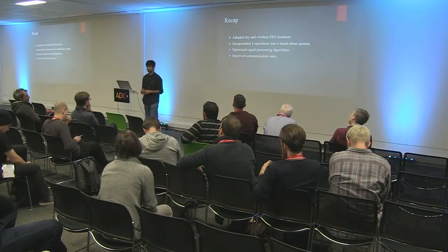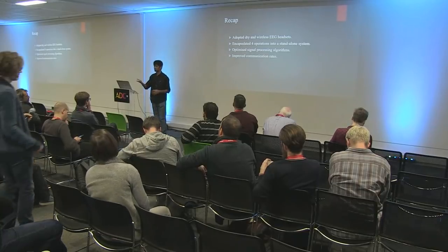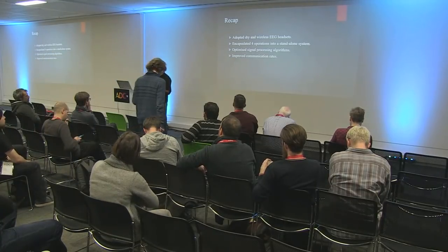Yes, that's an important point. You spoke about under 1 Hz, and the very low frequencies are related to motor movements. In this system, anything below 6 Hz is noise, and anything greater than 45 Hz is noise again, because you're analyzing up to 5 harmonics. So you're saying the very low frequencies correspond to hand movements and stuff like that, which should be filtered out.